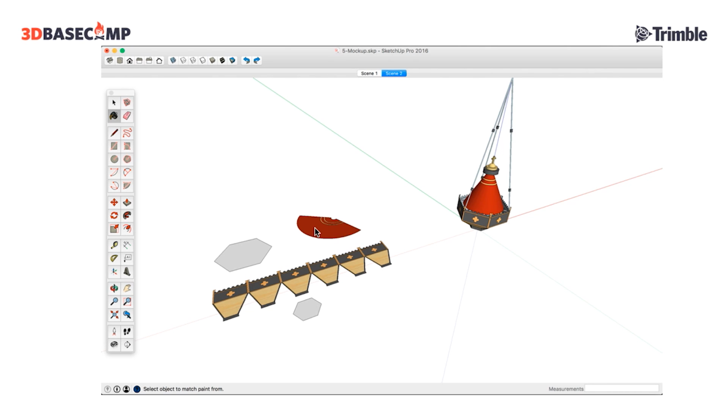So for here, I also included the hexagon of the top as well as the bottom just to give some support. Then I set a top view as a scene, brought that into layout, and set a custom document size for our plotter, so 24 or 36 by however long we needed, 72 or 60 inches. And then we just cut it out, spray mounted it, cut it out again, and wrapped it all together. That way you could actually take it up and hang it.